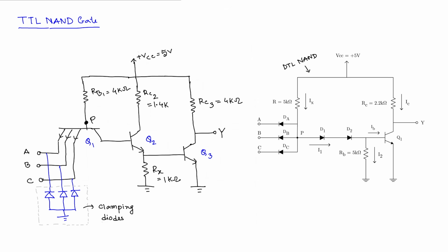And if you remember, for DTL, we saw that this particular resistor to ground, we deliberately use that so that whenever this transistor was in saturation and then suddenly the base current goes to zero, obviously there will be some charge stored at the base, and we have to somehow dissipate that so that we can quickly transit into another state. So that was done through this path. Extra charges were dropped going through the resistor.